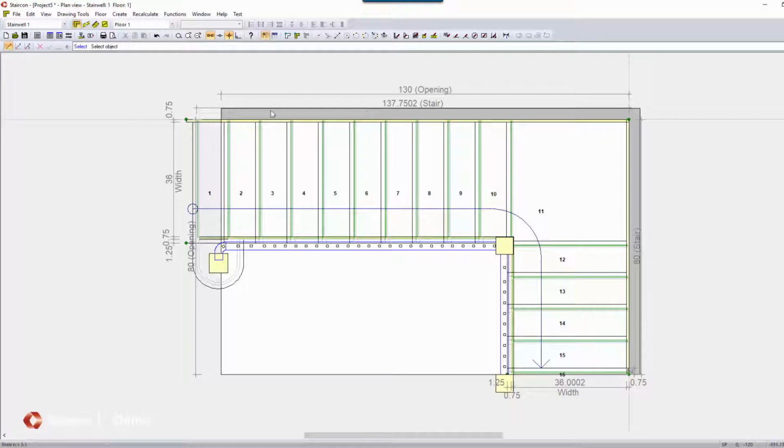So you see that the wall is not long enough, so we're gonna make it a little bit longer. And we have some options here as well to just snap it to existing items. But if I want to have it, let's say 5-inch from the nosing, I put in a helpline. You can snap to points, move it, and when you snap to points that are the same, like the walls and the floor opening, you can choose if you want to move both of them, or in my case now the wall by itself. So I just clicked on the wall and I moved it.